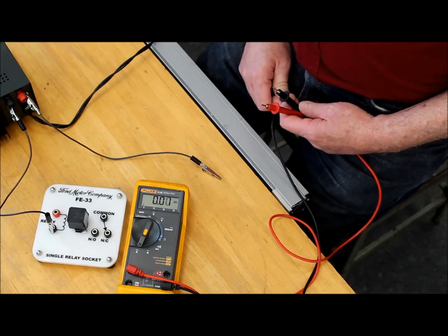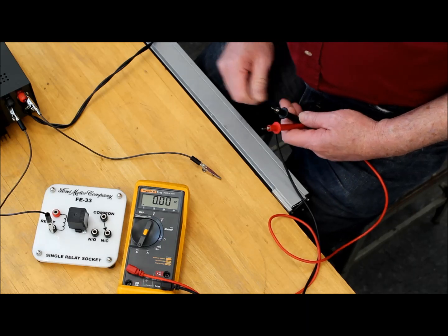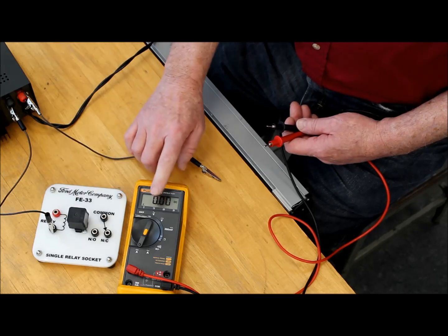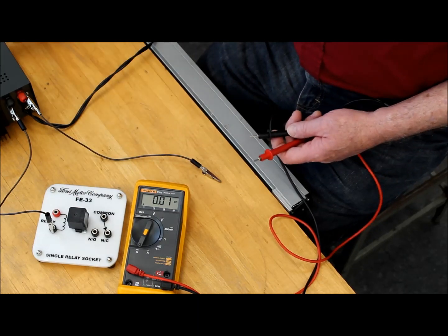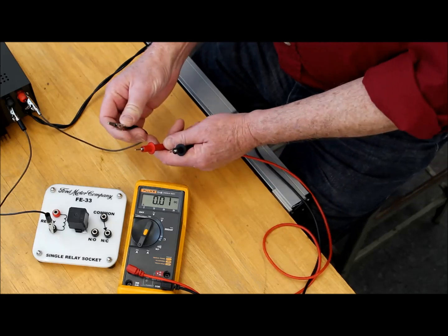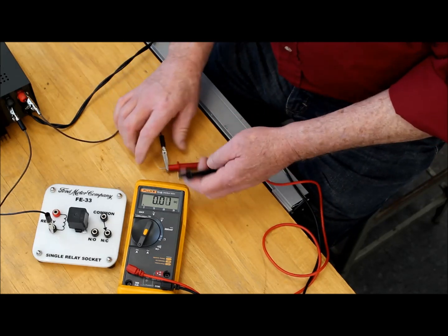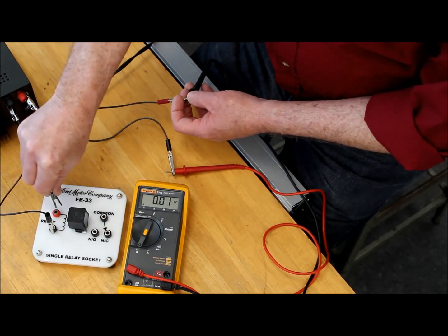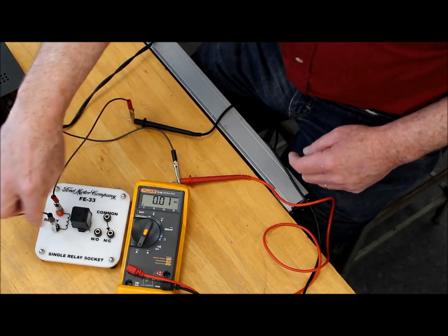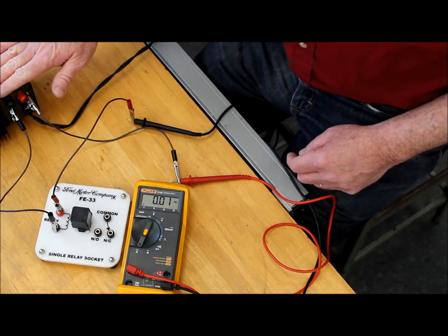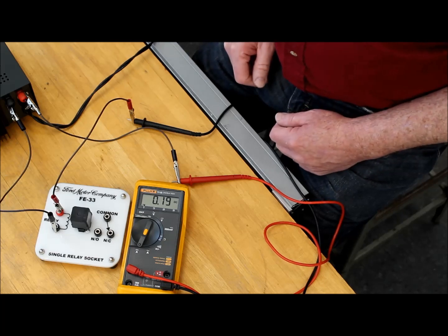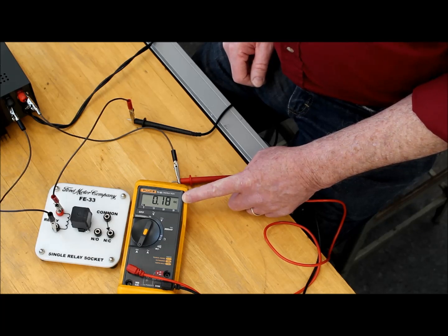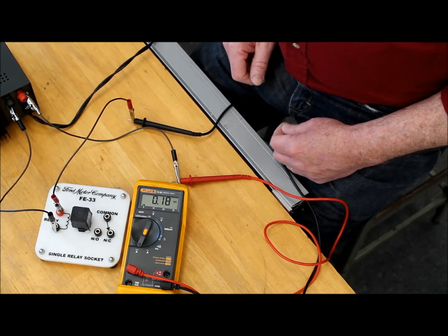Here we're going to see just how much current it takes to energize this relay coil. So I'm going to run current through this side of the relay, the coil side, but I'm going to run it through the ammeter on the way there and see how much that takes. So we're going to run from my power supply to the ammeter, from the ammeter then to the coil, and of course the coil has a ground on the other side here. So when I turn this on, it's 0.19 amps DC to energize that relay coil.